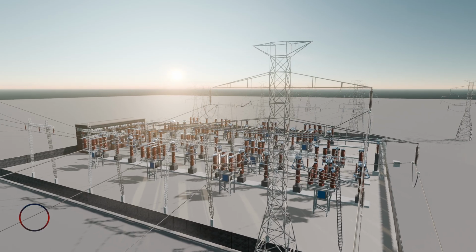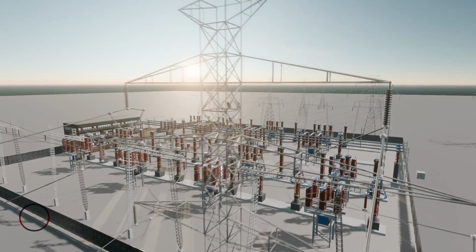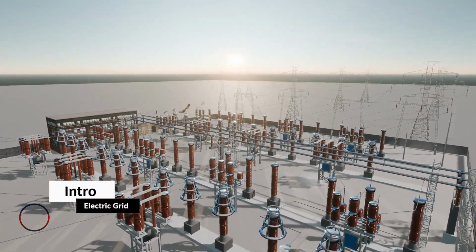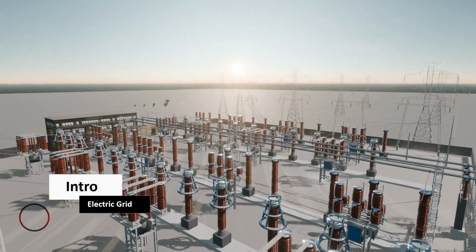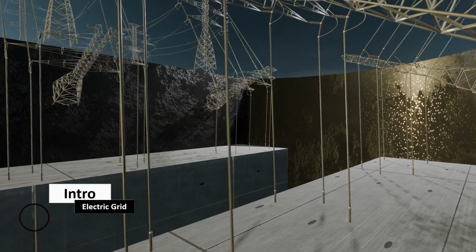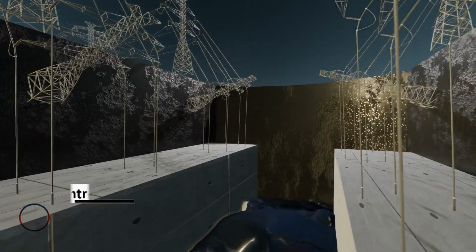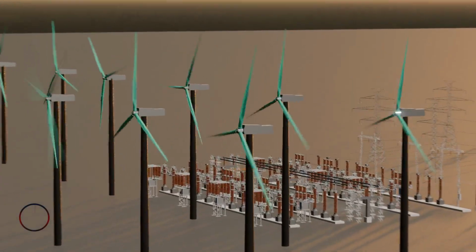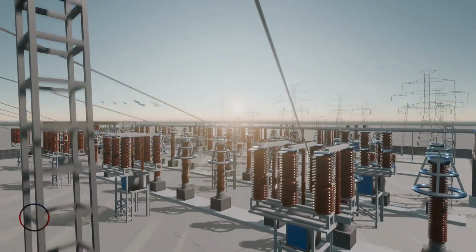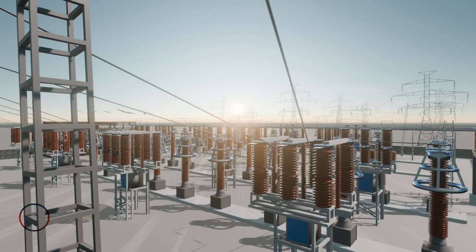The electrical grid is the interconnection of several generating stations together in a network in parallel. That is, the electrical energy that is generated in thermal power stations, hydropower stations, nuclear power stations and wind power are connected to a common network in parallel before it will be further transmitted via transmission lines to power substations, and to the final user down the chain of transmission.